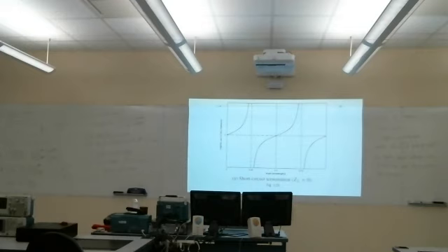Okay, so it doesn't act like an inductor over a wide range of frequencies. It doesn't have the same frequency dependence, but at a particular frequency, it has a positive jX impedance, just like an inductor at that frequency would have. So if you're just transmitting using a small range of frequencies on your transmission line, substituting this piece of transmission line for an inductor actually works.